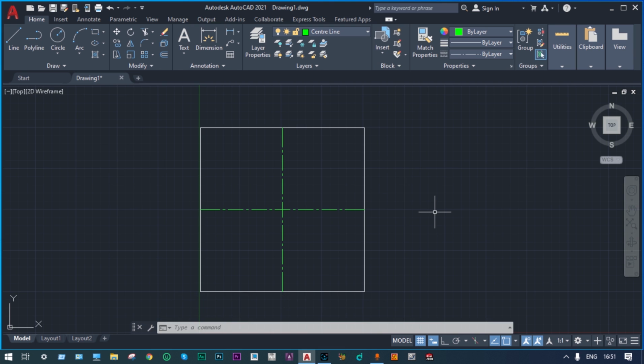Next one, you can see sometimes it may so happen that lines are not properly visible. It may so happen the line is not properly scaled. So to have a better scale of these line types, we can provide a specific scale for these special lines. Sometimes the lines may not be visible. If the length is very small, the lines will look like solid types.